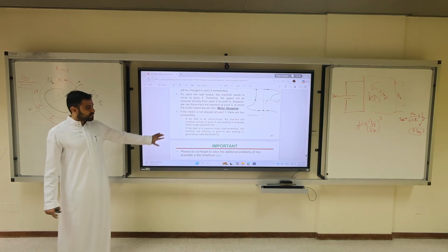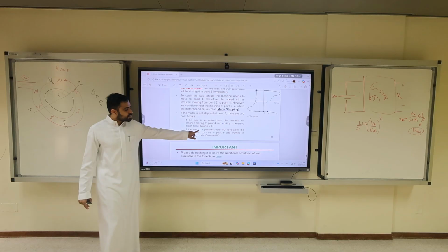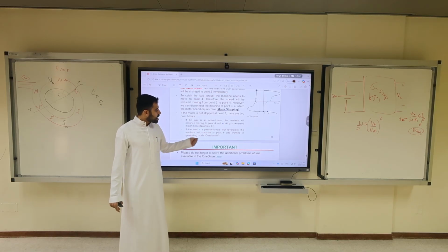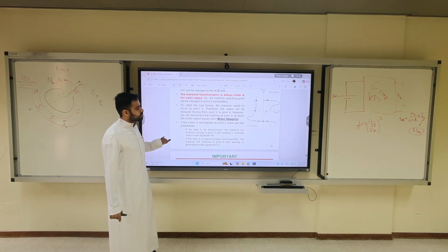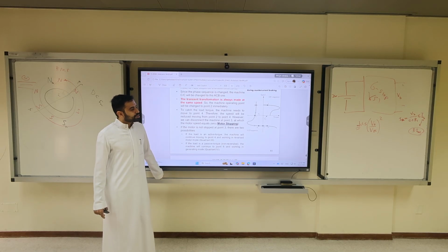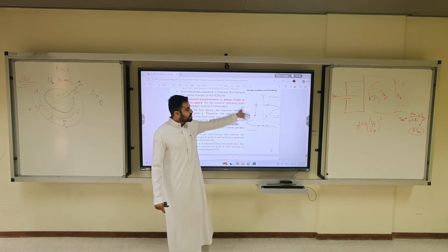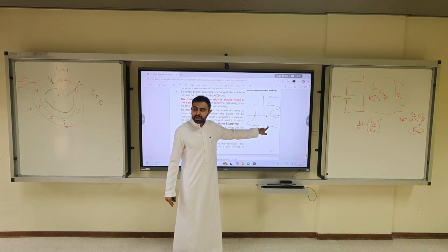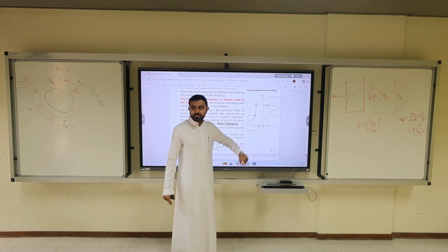This is side information. If the load is passive torque, non-reversible, the machine will continue to point 6 and working in the generating mode. Because the torque is non-reversible. It cannot have negative torque. So you have to go through this cycle to make the torque here, to reach this curve. Okay?